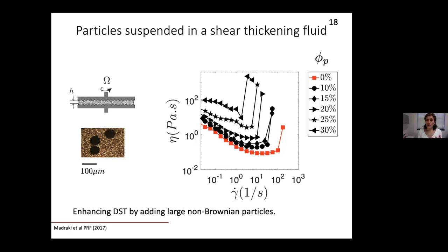And if the repulsive force should balance the shear stresses in the suspension for that friction to become activated and that jump to happen, now that occurs at a local shear rate, not at the average shear rate, and the average shear rate associated with the critical local shear rate obviously is smaller as we add more and more particles.